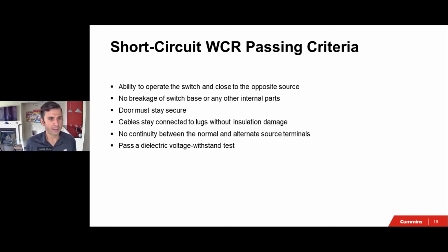And it's expected that after you experience a short circuit with this WCR test, you would replace the transfer switch. And most importantly, that no one gets injured or no damage or fire or burn happens if we experience a short circuit. And also we need to have the ability to transfer to the alternate source if we need to.